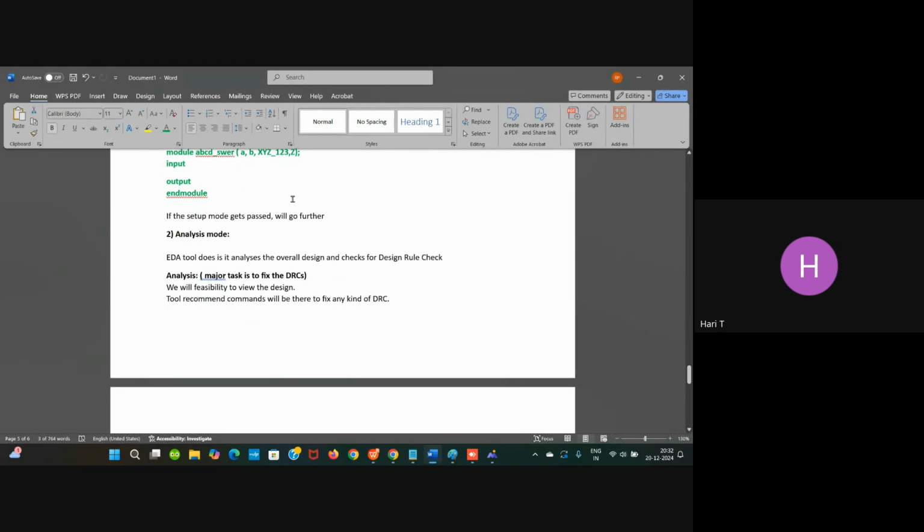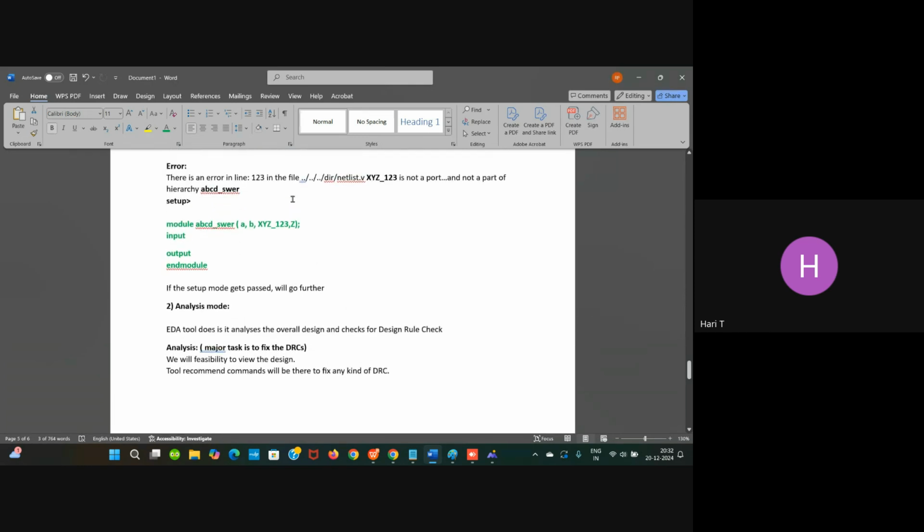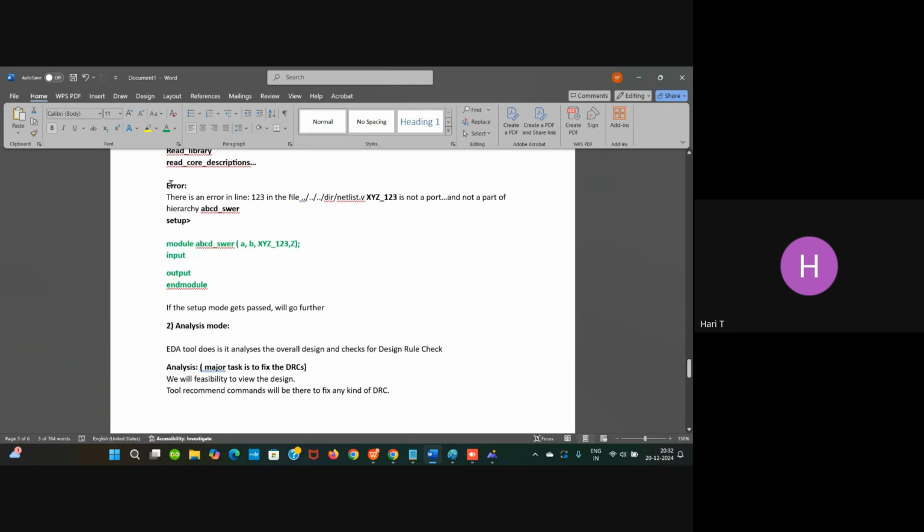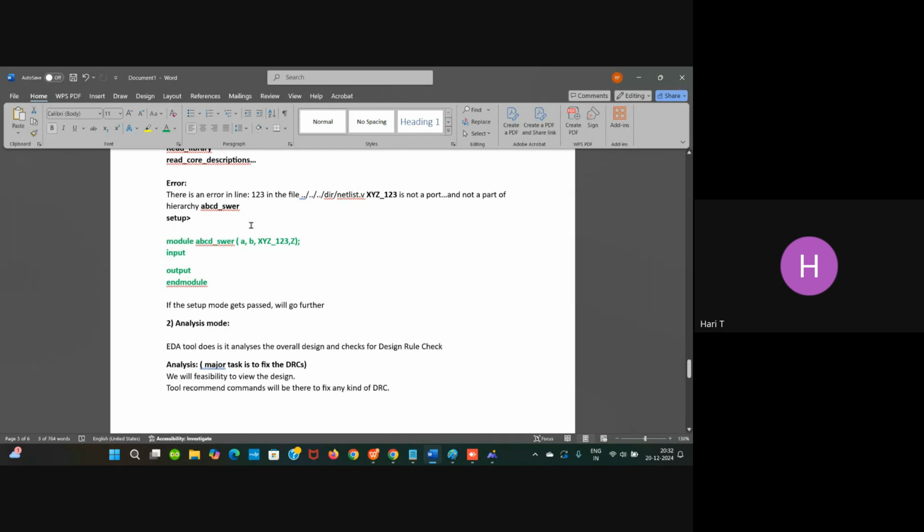For example, some files are missing in the given IP directory, or in this particular RTL file there is no such module that you have defined later in the Verilog code. You can send the screen snip of the error statement to the RTL engineer so that they will understand, retrieve the code and give it back after fixing it.